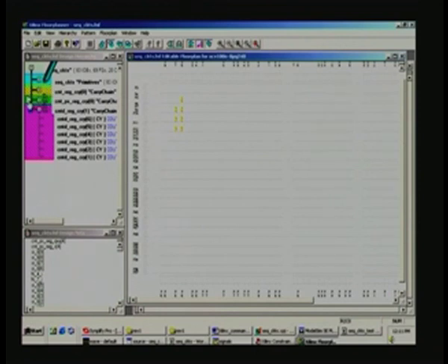Anyway, you experiment, I will leave it as an exercise to you, and the main emphasis here is, suppose you are not happy with the frequency of operation that you have already achieved in spite of synthesis, you can get extra mileage by placing different parts of the design at other strategic points, probably very close to the pins, and you can also renumber the pins, and all this will be an added advantage by redoing the floor plan.